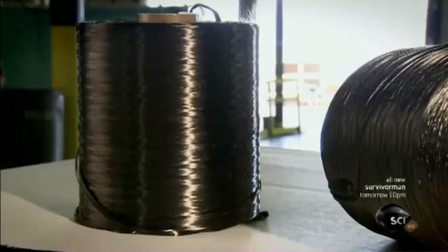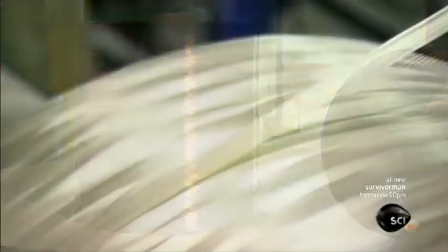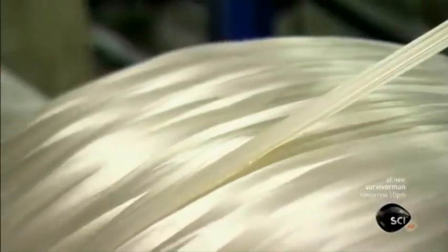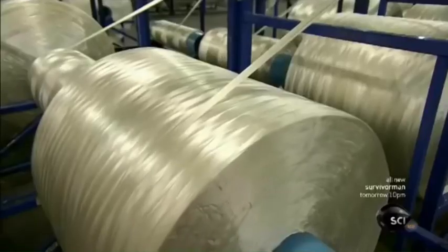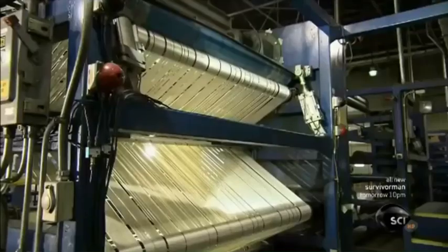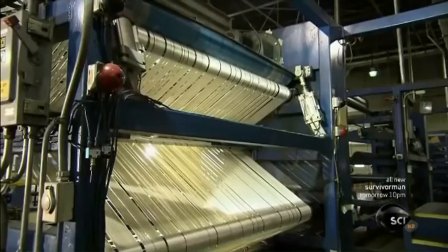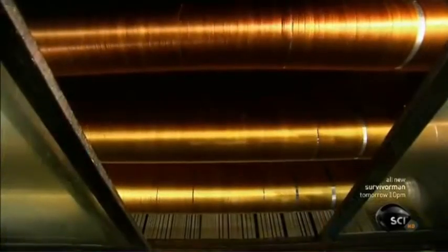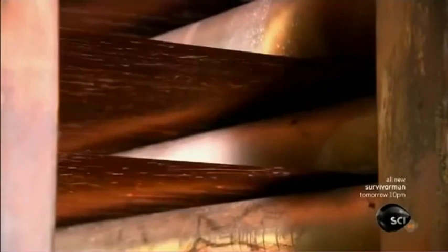Carbon fiber is 5 times stronger than steel, yet less than half the weight. To make it, they take a plastic fiber composed of thousands of filaments, far thinner than human hair. They then chemically alter it to form a perfect chain of carbon atoms for the final product. This mammoth machine lines up dozens of those fibers, which then travel through an oxidation oven for a couple of minutes. The oven temperature, about 480 degrees Fahrenheit, prompts the fibers to pick up oxygen molecules from the air. This rearranges the fiber's atomic structure, rendering them resistant to high heat.